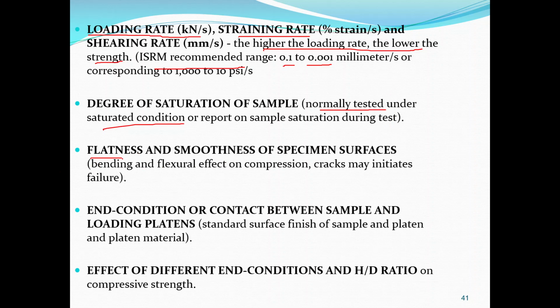Third, the flatness and smoothness of a specimen. Make sure that if you have a core specimen like this, the bottom here and the top here must be flat, because the end condition of contact between the sample and the loading plate must be good. The surface finish of the sample and platen is very important, so flatness and smoothness.